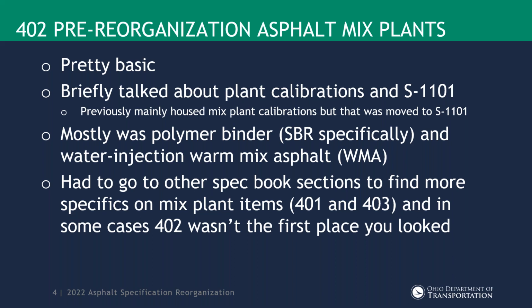So, well, let's jump into 402. Pre-reorganization 402 is, I would say, pretty basic. It kind of briefly talks about plant calibrations and references Supplement 1101. Supplement 1101 houses our plant calibrations. 10 years ago, the spec book 402 actually had the mix plant calibrations in it, but we pulled those out. The supplement's just easier to update at that point. Then it talked about some polymer binder. It had a section on polymer binder, which was basically SBR specific. And then it mentioned water injection, warm mix asphalt.